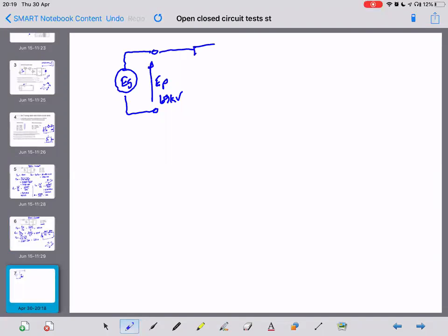We've got an R component of 150 ohms and an X component of 632. They represent all the losses, the primary and the secondary series losses.